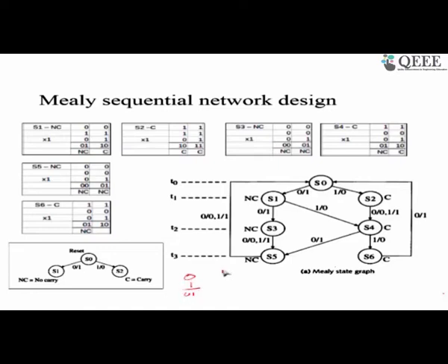On the other hand, when the input is 1 and because we have to add a 1 for the XS3 conversion, we will have an output of 0 and remember this carry. So what we do is, from S0, when a 0 occurs as the input, we output a 1 and go to a state where we remember that there is no carry.